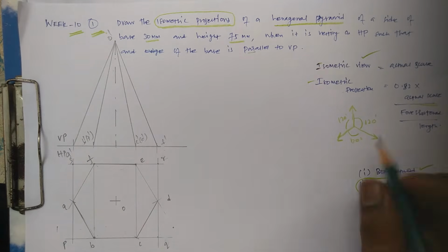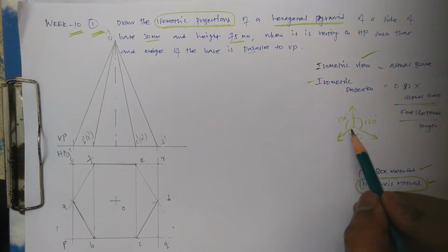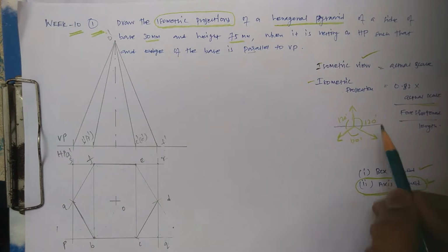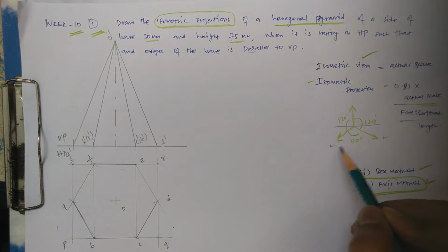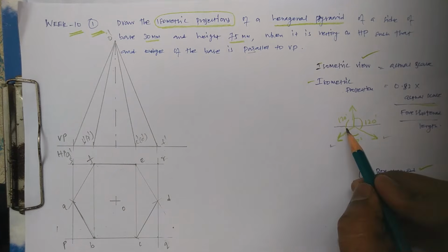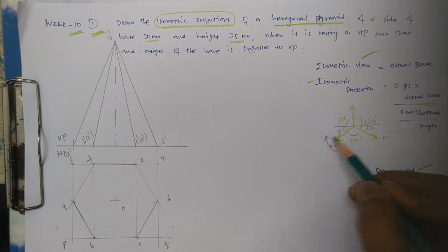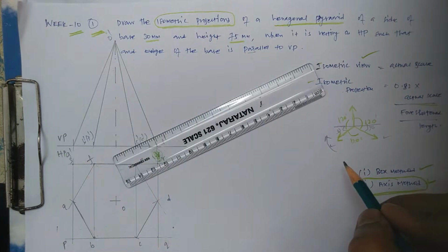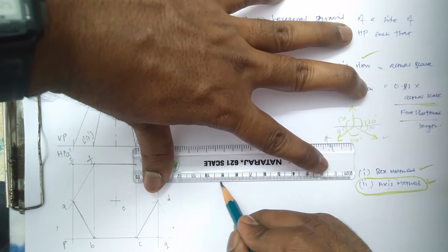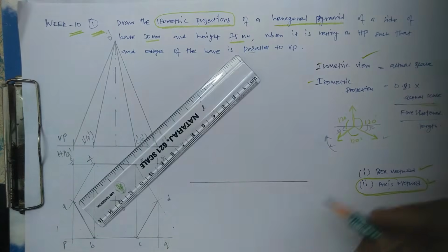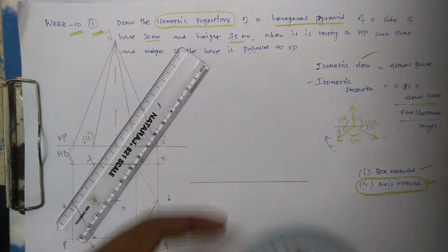So now we need to draw the isometric plane. As I already started here, the axes of isometric, when you are looking at these two axes, let it be X and Y, we can fix that. That means when you are cutting here, this is 90, remaining is 30 degree. This is 30 degree. To draw the same diagram, I am going to use one horizontal line as a reference line, and on both sides there is a 30 degree angular line.